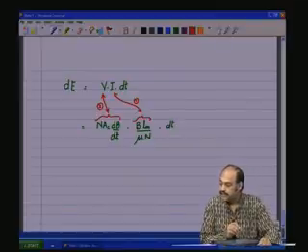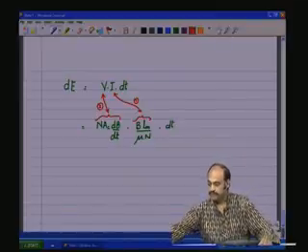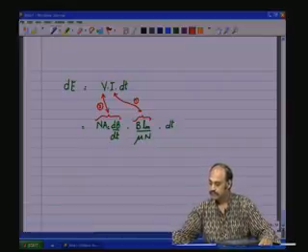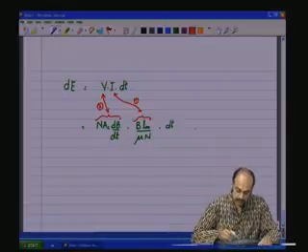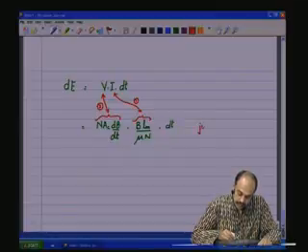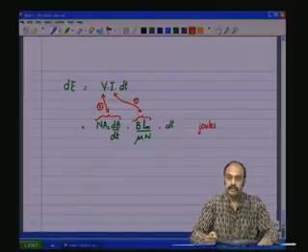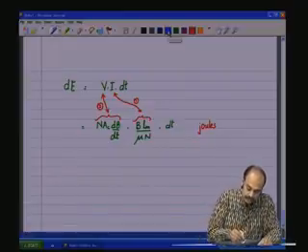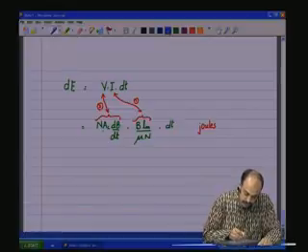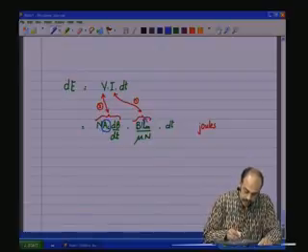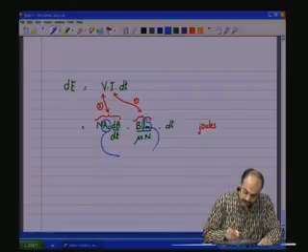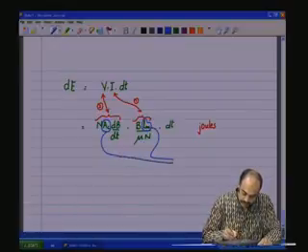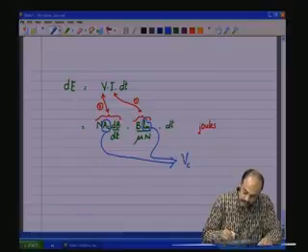This is the instantaneous energy. This is having units of joules, instantaneous energy in the core. Now, here Ac and Lm, magnetic path length and the cross section area together give the core volume Vc.